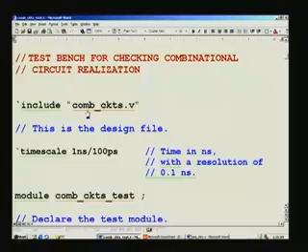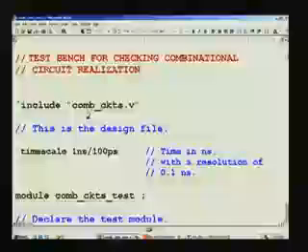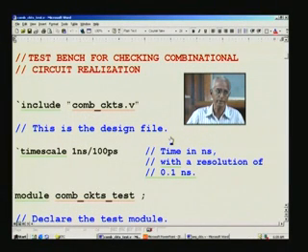We are going to simulate your code. What we are going to do here is stimulate it, that is, apply different pulses with reference to different times. So there must be some time base to tell the system that you want a time base of, say, 1 nanosecond. For that you have another statement, once again a tick and timescale, with a space, then say 1 nanosecond, or 1 microsecond, 1 us, and you can also specify how much resolution you want.